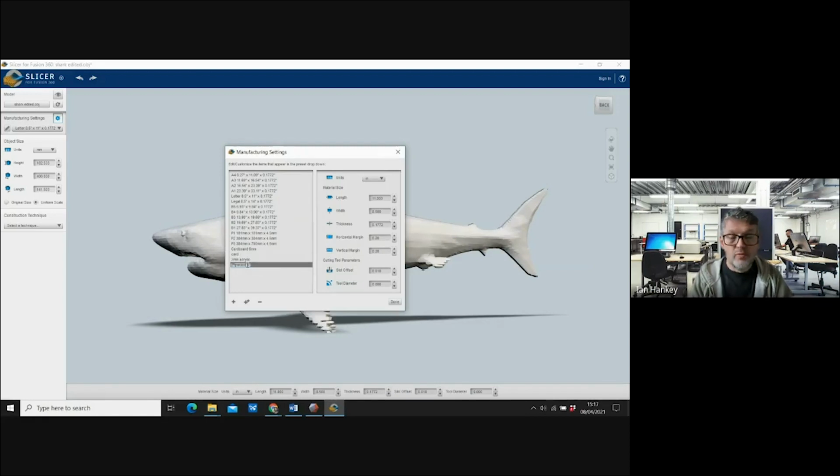Okay. I'm going to put 4 millimeters, which is my thickness, then a times, and this is 500 across, and times 375, I think it is. And then I'm going to press enter. So I've now got a field on the right-hand side, which is linked to the plywood, because this is what's live at the moment. So on the right-hand side, we've got this column. All of these things relate to the plywood settings. Now it's in inches again. So I'm going to go up to there and click that, and change it to millimeters because that's what I'm used to.